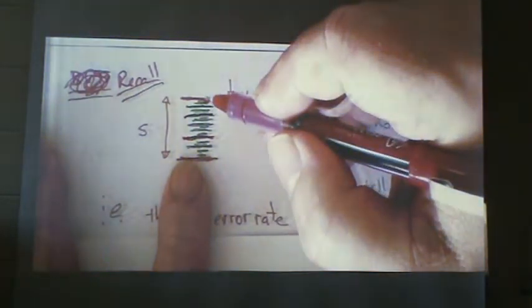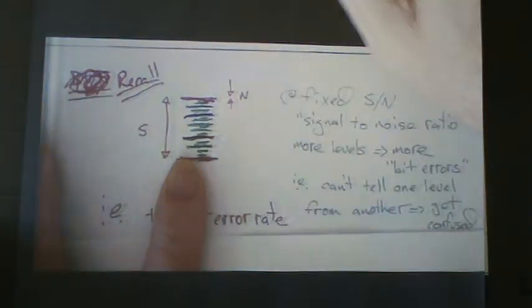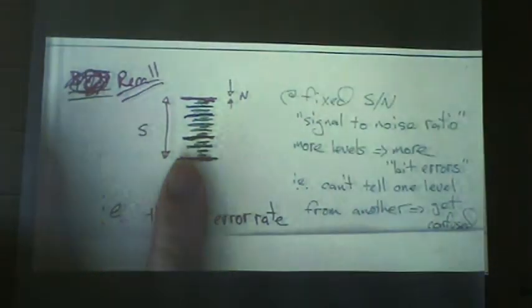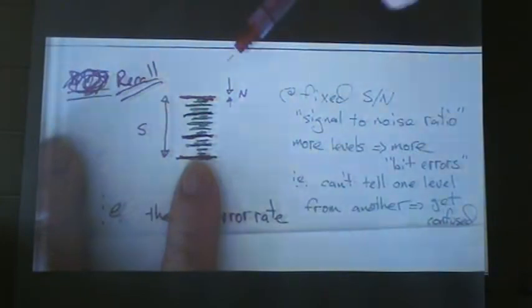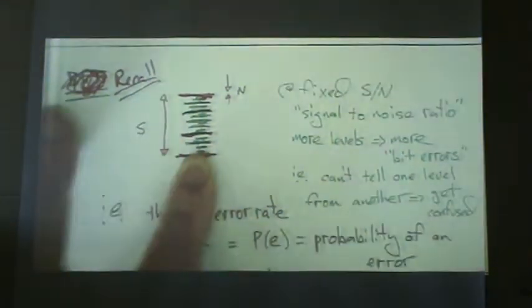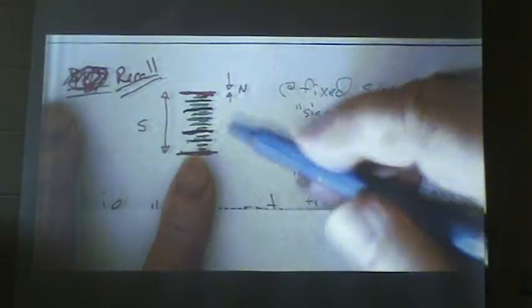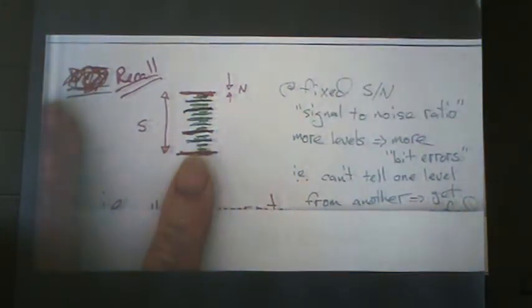That's one of 4 things would be 2 bits of information every T seconds. I just doubled the number of millions of dollars a month you could make in the same frequency bandwidth, right? Because frequency bandwidth doesn't depend on that, that's separate from the data rate. Frequency bandwidth always goes like 1 over capital T. Capital T is the distance between the bits. Right? The distance between the pulses, the distance between the sample times, in other words. Right?